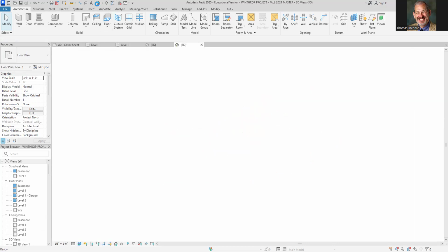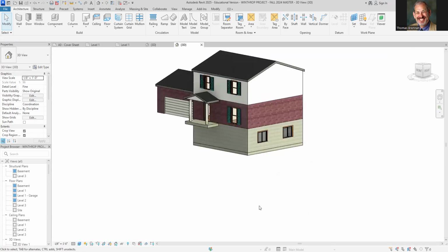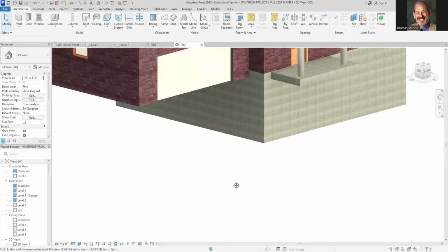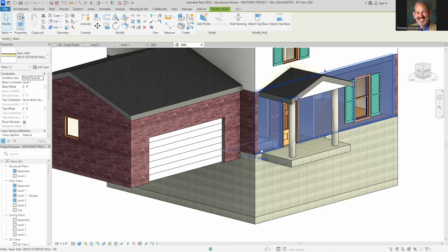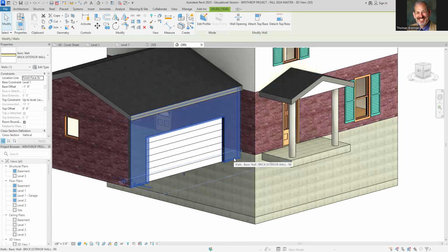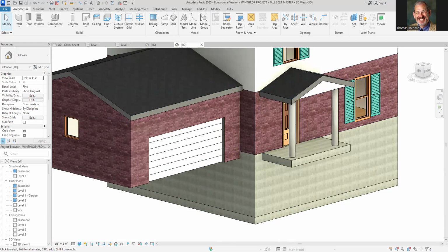Notice what you've got going on here as you take a look at this. You've got this, and you've got something going on here. Notice the difference that we have right here. You'll notice that this wall right here is here, but the wall for the garage is lower. Now, why is that? Why would the garage be lower? What's that? It has to be anchored in. Yeah, well, it's good. And the other thing, because you want to drive your car into it, so you're going to be coming right up there. And then the porch is higher up because you don't want to have water come in. So therefore, there's going to be a difference. And so there is. So that means that these walls that make up the garage, they're lower.